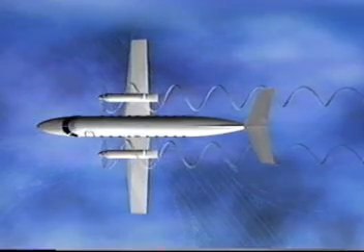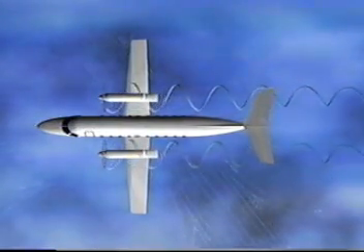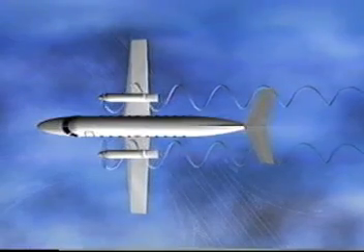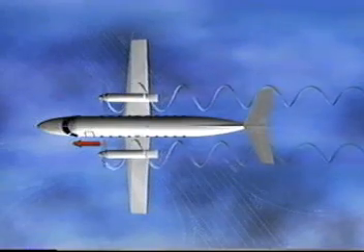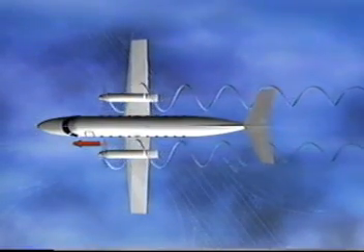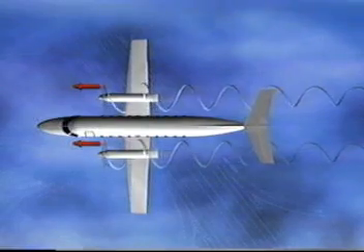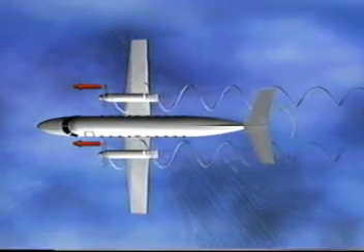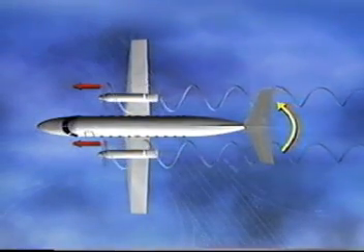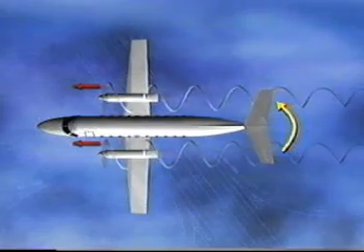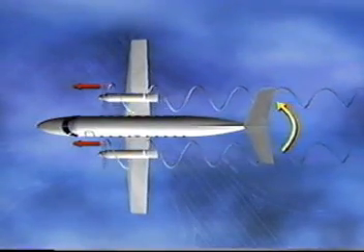Consider also the offset of thrust created by downward moving propeller blades developing more thrust than upward blades. This results in that the center of thrust of the left engine is closer to the airplane fuselage center line than that of the right engine, because the right engine has a longer arm than the left engine. Another component of yawing force appears. Realize that when the left engine is inoperative, there is greater yawing force than if instead the right engine is made inoperative. All these effects make it urgent for the pilot to use properly the elevator and rudder to prevent all pitching and yawing forces created.